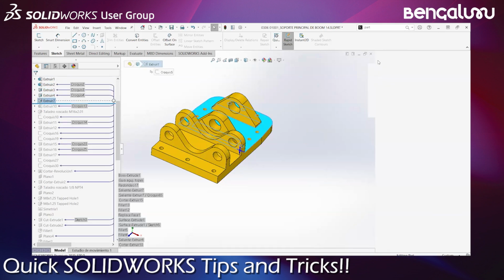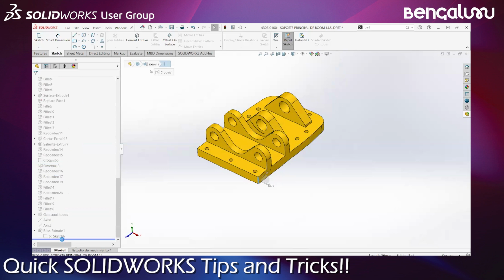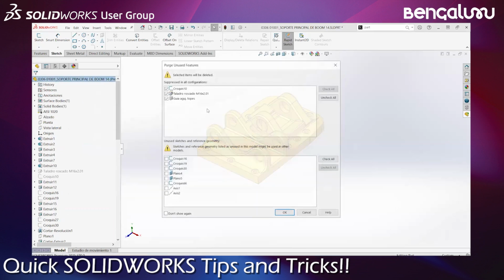Yeah, so this is again one more effective thing. I have used this a lot in the past, and it really helps a lot. Right? Okay, so I'll just put it back where it belongs. And on similar lines, when you right click on any part, right, we have this command which is called purge unused features. So once you click on it, this particular tab opens up.